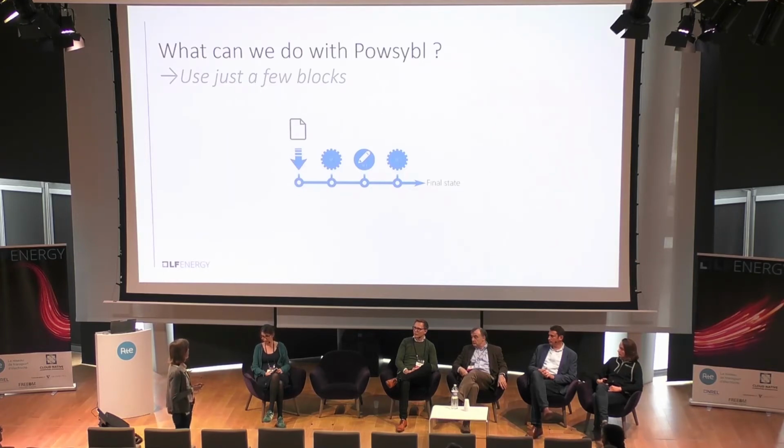You can then simulate a contingency, for example, the loss of a generator or the loss of a transmission line. And then you rerun a load flow to see the differences with the previous state, and then you can see where you have to look in your network during operation, to have a secure operation.